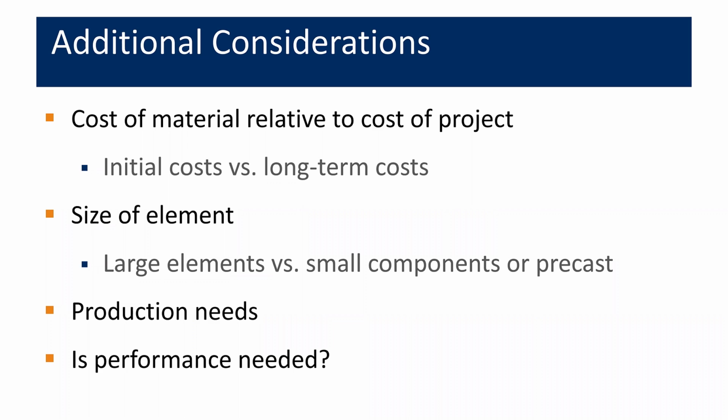If you're making a temporary structure where you don't need long-term durability, UHPC might not be the best choice there. Alternatively, if you've got a structure in a high corrosive environment or a place where durability is necessary, or an application where you are going to be relying on the tensile strength of the material, UHPC might be a better choice over some alternative materials.